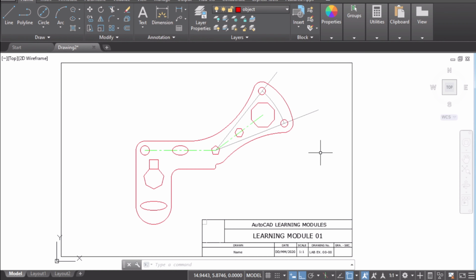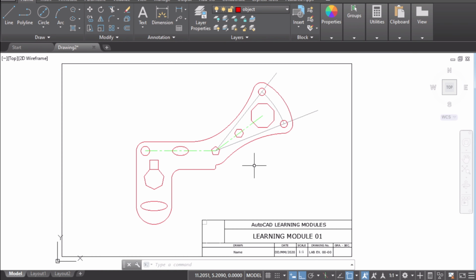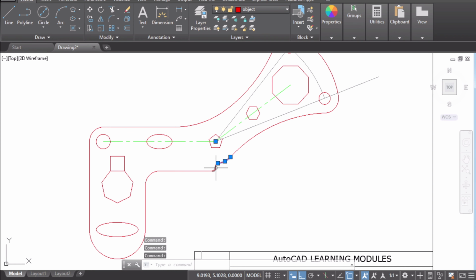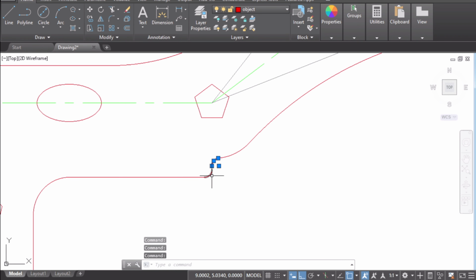And the last thing that you're going to do in this activity, once you finish everything, is to apply the Polyline command over here. So why are we using Polyline? Just because if you check this border, you can see it is very segmented. So everything is a segment, and we connected these things together.